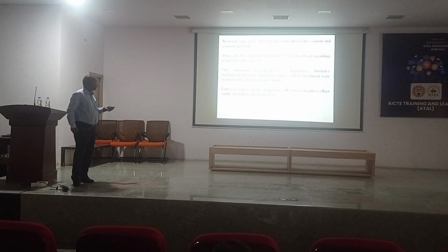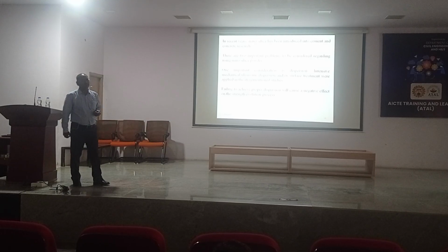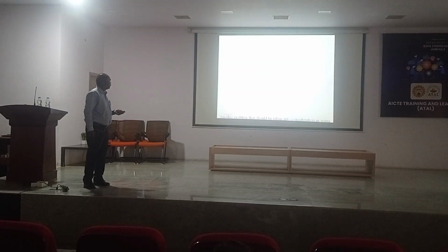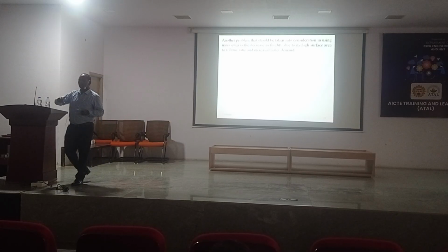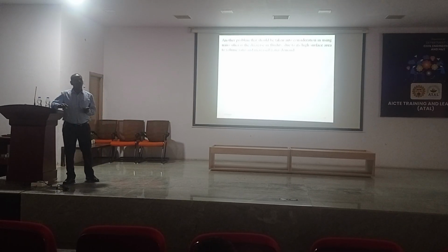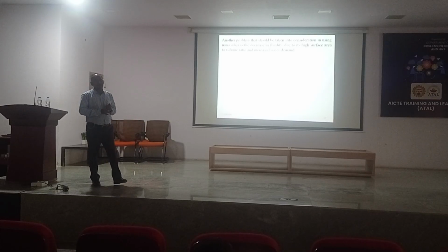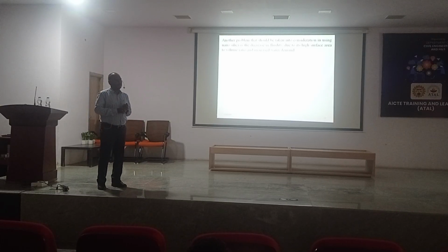Failing to get this dispersion will cause a negative effect on the strength. It's a wastage of money. Another is that more water is required because the nanoparticles have more surface area. Therefore, a greater amount of water is required, and it is less workable. If it is less workable, you cannot use that material as a repair material. Those are the two disadvantages of using nanomaterials.